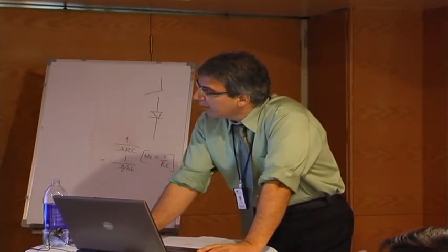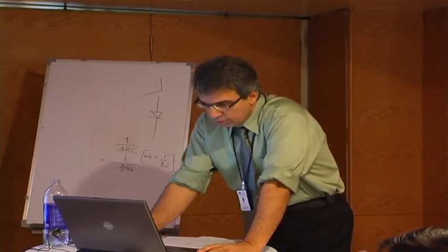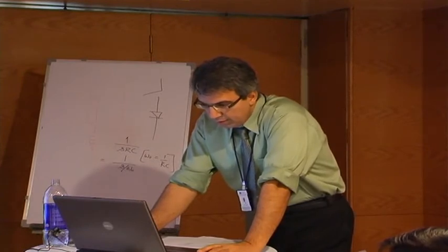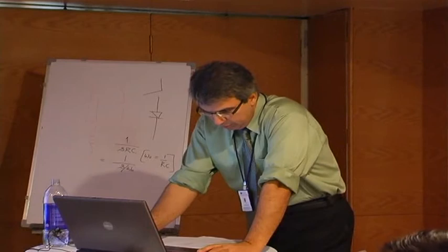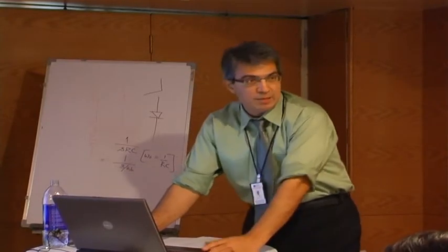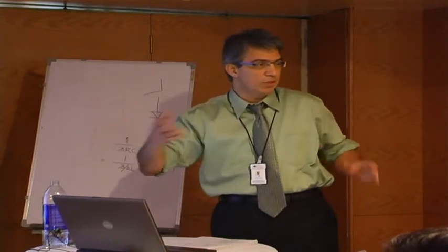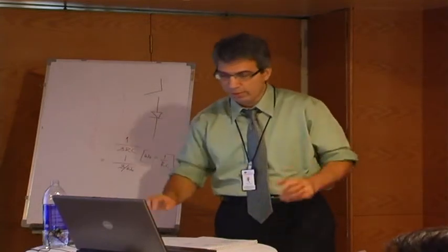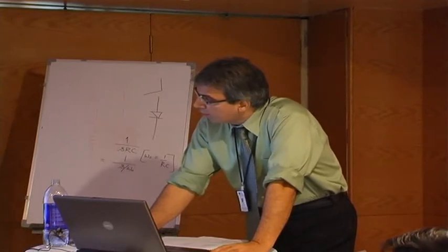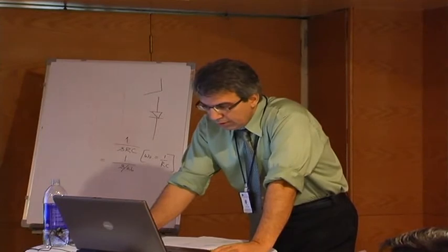And then the probe window is where it will show the results. You can set this up also. You can choose display probe window when profile is opened, or display probe window after simulation is completed. You can also do it during simulation, but then the simulation becomes very slow because it has to display results while it's simulating. And then you can also choose show all markers, on open schematic, last plot, or nothing. Right? So let's go ahead and simulate this.